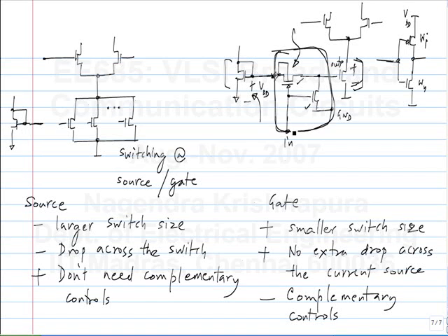Actually, see, this control, unlike in a regular PMOS inverter, is connected to VDD and this will go between 0 and VDD. In this case, the supply terminal of the inverter is connected to this VGS, whereas the input still goes between 0 and VDD. So it will effectively switch off this transistor and switch it on also. There is no problem with it.